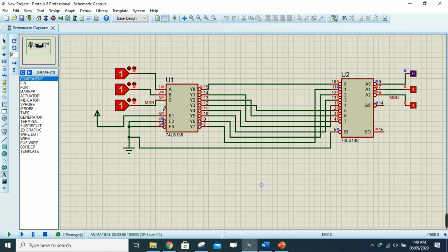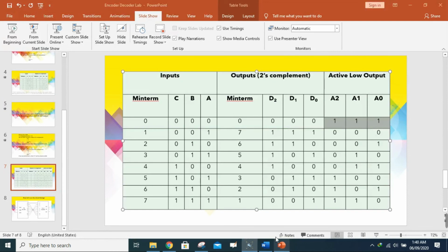that's why it's blue. At the input side, you can see that the active connections are indicating red, okay, but at the output side you can see that the active one is indicating as blue. Okay, so Y7 is the active one right now because we gave the input as 1 1 and 1. So at the decoder part we are getting 7 as our output. Okay, but if we want to do the 2's complement for 1 1 and 1, then we'll be getting 001 as our 2's complement representation.